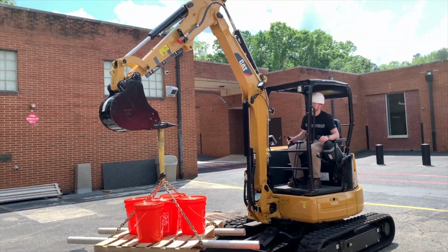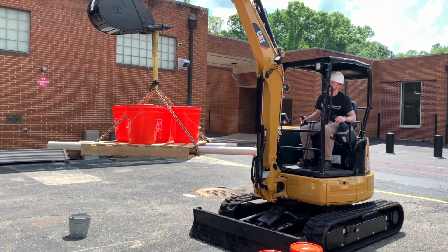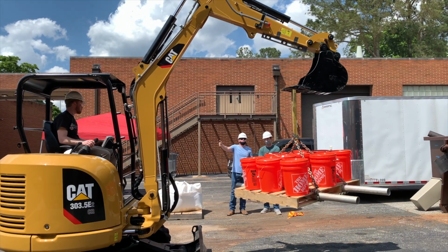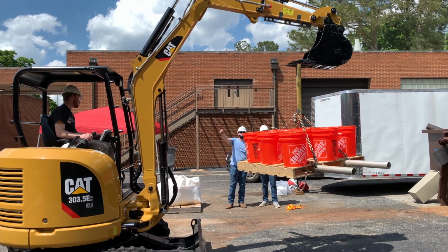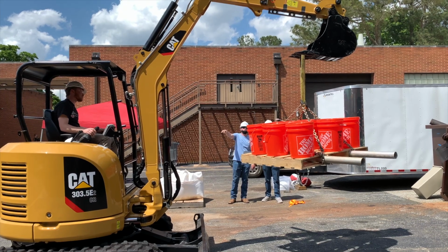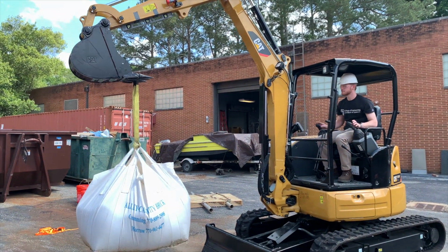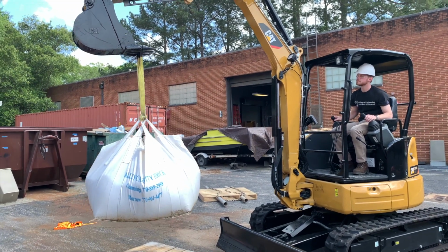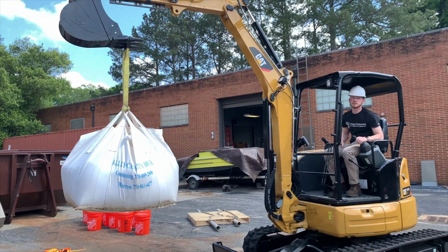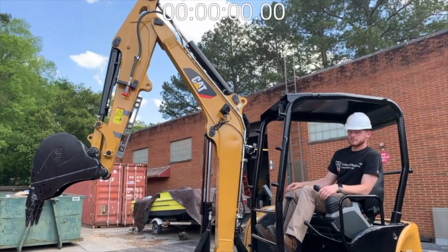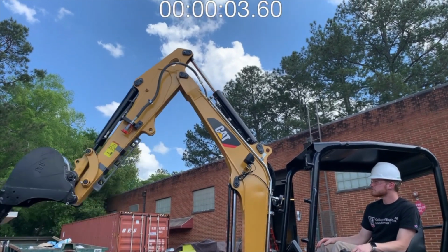And then using this pressure along with the geometry and the static setup that we developed, we could predict the weight that the excavator was carrying and then compare that to the known load of the weight that was predicted before the lab started. For the dynamic loading, the idea was still to isolate the stick cylinder. So the same position that was used in static was used in the dynamic, except here we would take the stick cylinder from fully extended to fully retracted and vice versa, and measure the time it took to go from one to the other.